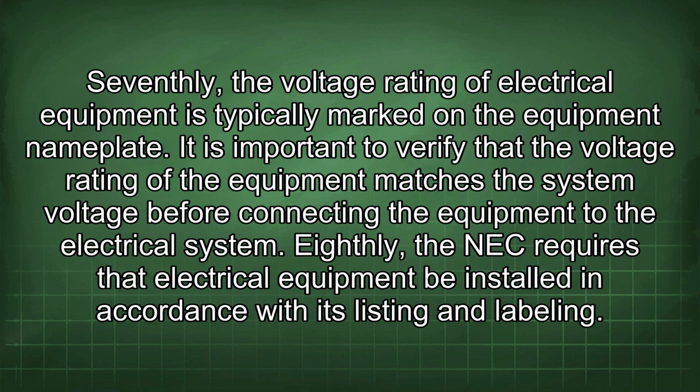Seventhly, the voltage rating of electrical equipment is typically marked on the equipment nameplate. It is important to verify that the voltage rating of the equipment matches the system voltage before connecting the equipment to the electrical system.